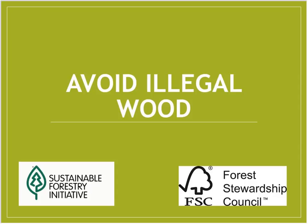So, some real specific things: the whole idea of avoiding illegal wood. If you can work with your client to spec wood that's local to your region, ideally, if not local to the country, or at least within Canada. If not, then many programs require at the bare minimum that you use the Forest Stewardship Council certification, which is a third-party chain of custody certification that ensures wood wasn't harvested illegally.